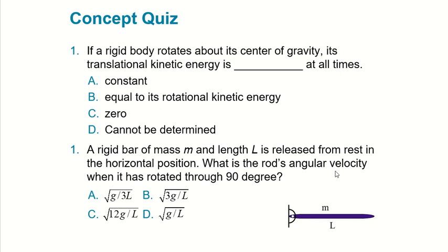If you calculate it, using your angular velocity relationship with your length and the mass, you're going to get the square root of 3g divided by L, which is your length, okay? So this is your center, and that is your length, kind of like a radius, and it's going down that way, okay? So you have an angle, let's say starting from 0 and then keep going, okay?